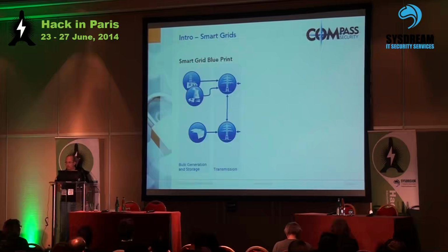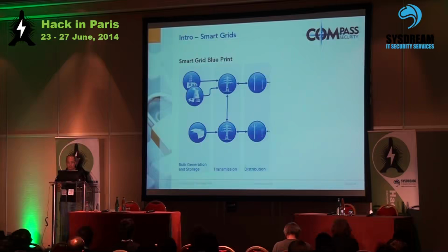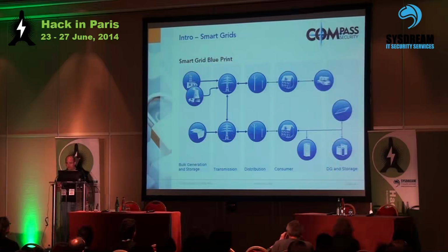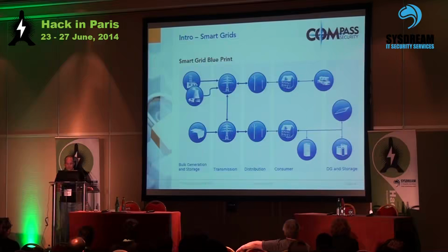And there it's going to be interesting because we do have lots of consumers, and people try to get their own energy into the grid and sell it to the DSO. They are starting to also virtualize the energy infrastructure. So they build little VPPs, virtual power plants, where they try to arrange consumers and producers in little cells. And for that purpose, you must somehow make the grid intelligent. Therefore you need the smart metering infrastructure, so you have proper, real-time information on what is currently being consumed and generated at the far end of the grid.